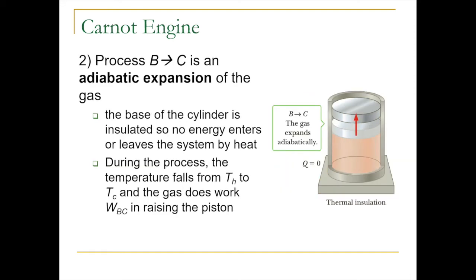From there, we get into the idealized version of the Carnot engine by replacing the hot reservoir with thermal insulation, which stops the exchange of heat between the cylinder and the outside environment. Even though this has happened, there is still going to be a natural expansion of the gas, but now it's going to be done adiabatically, in that the work is still being done by the gas on the piston to raise it up, but now the temperature of the gas is going to change from the temperature it had from the hot reservoir into a different temperature, which we'll call T cold.